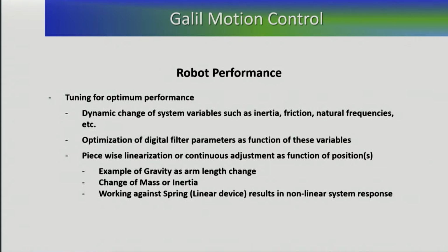Also, if there is an arm that basically has a movement that goes over the 90-degree travel, then the impact of gravity and the compensation can basically go both ways. So you need to be able to look at that, and the controller allows basically the ability to address those as part of your friction's resistance that you would have.